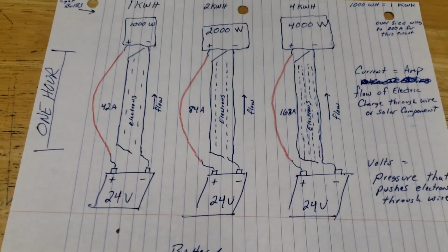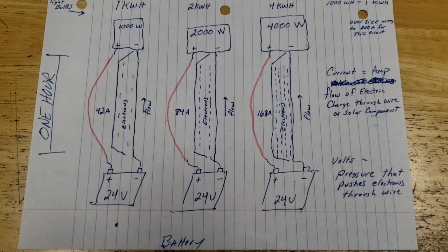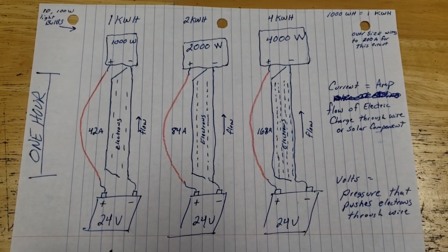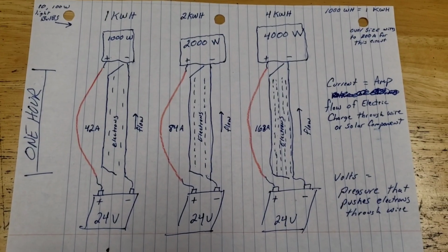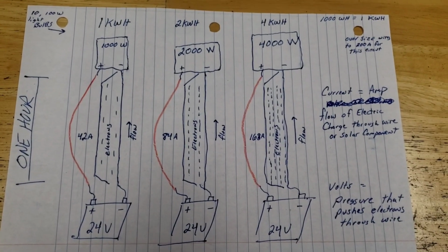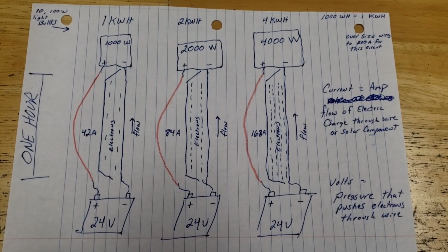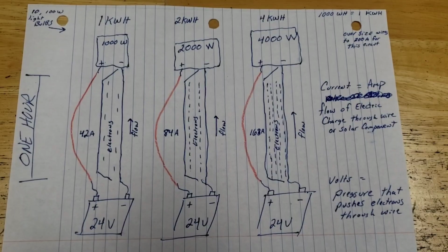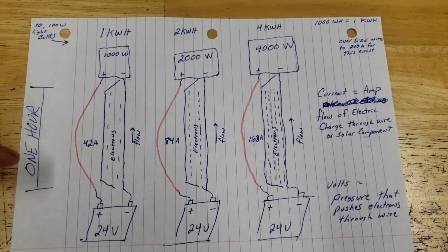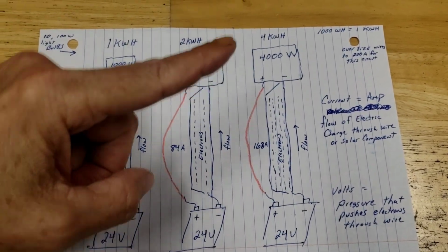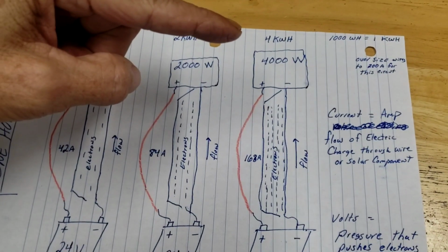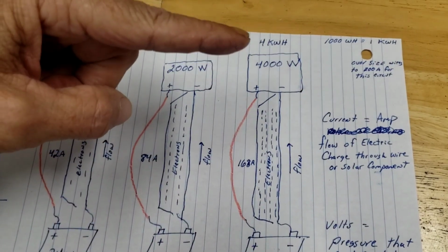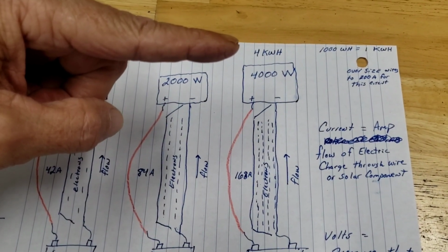Now, if you all go get your electric bill and look at your power company bill, it's all based off of kilowatt hours. And the going rate is about 15 cents apiece. But this is a real good visual for learning about your electric dryer. So you throw a load of wash in there for 1 hour. We already know we have our time frame, 1 hour. Your electric dryer is 4,000 watts. If it runs for 1 hour, it's going to use 4 kilowatt hours.